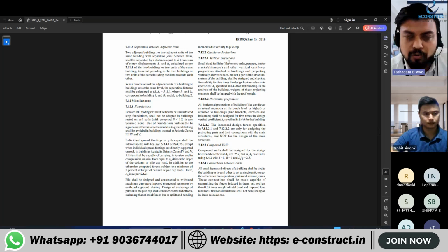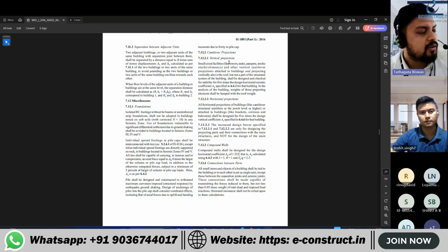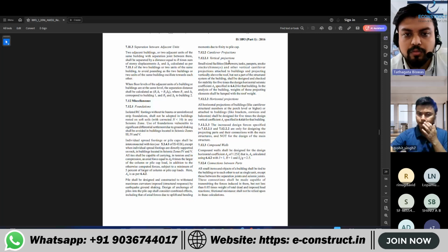So that's why we just follow the density, calculate the load and put it on the beam. We couldn't model that because of the property issue. Masonry property is there in ETABS, but it is a property from some other code maybe.